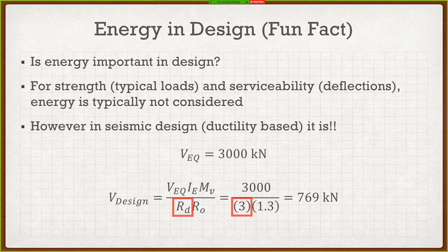Study, catch up? Oh, Johnson also says for taller buildings, how did they prevent shear from traveling up the tower? Actually, if you study shear in tall buildings, the opposite happens. If a building is hit by an earthquake, the maximum shear actually increases as you go down the building. At the top of buildings, there is very little shear. It's basically just the bottom of the building that you're worried about. Because if you think about an earthquake, it's moving the ground back and forth, so a building is basically just a giant cantilever beam. That's where all those maximum loads are going to be, at the base.